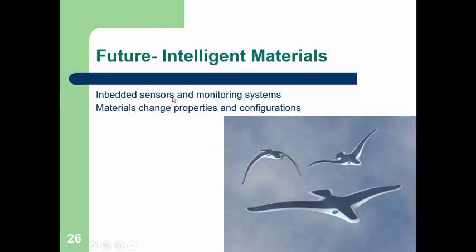But for health monitoring in composite structures, when they build a wing structure, for instance, they embed these sensors in it so that it can tell the maximum stress that's been put on that wing structure, and from that make some decisions about maintenance and replacement of parts.